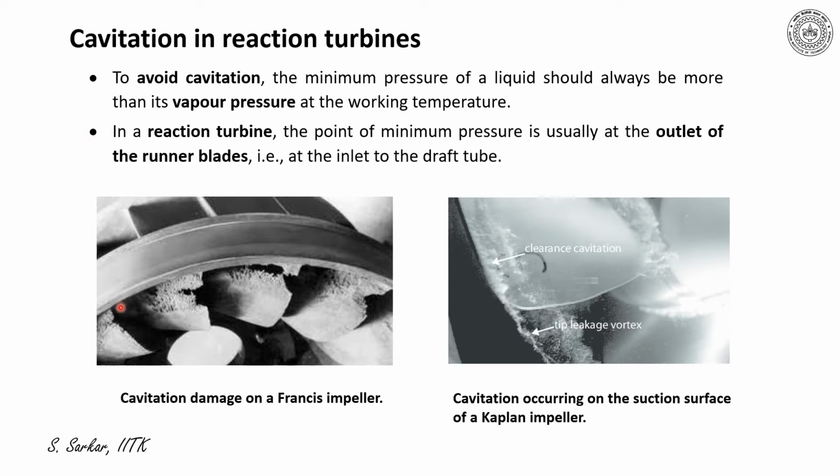I have indicated here the cavitation damage that has occurred on a Francis blade. One can realize the damage is significant at the outlet of the turbine. Furthermore, I have indicated another picture illustrating the flow visualization that shows that a cavitation bubble has formed on the suction surface of a Kaplan turbine.